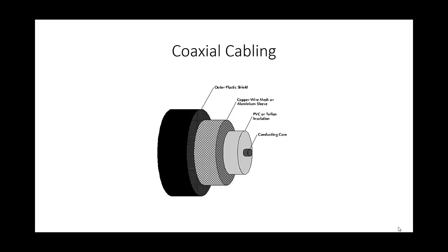There were two types of coaxial cabling used for early implementations of Ethernet, referred to as thicknet and thinnet. Thinnet is flexible and looks much like TV aerial cable, but thinner, approximately 0.5 centimeters in diameter. Thicknet is less flexible and about 1 centimeter in diameter. Thicknet offers better protection against electrical interference and so supports longer run lengths of cable. Both types of cable support data transfer rates of up to 10 megabits per second and have an impedance of 50 ohms at the operating frequency of 20 megahertz.